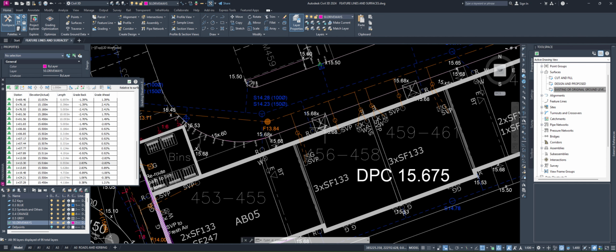The problem is we're slightly higher at this end, and when it starts raining, all the water is going to run down this way. If we're using flat top edges, I know for that specific model they're going to be using bull nose edges with the 25mm upstand, but again I prefer adjusting the line slightly more, putting the edging line slightly down from the finish floor level, and not a lot. Again, it has to be a level axis for the disabled purposes.